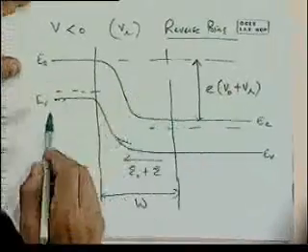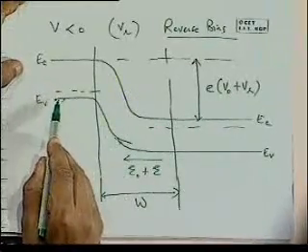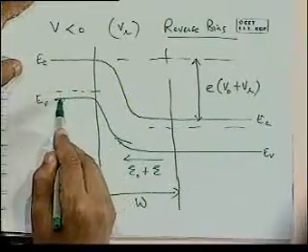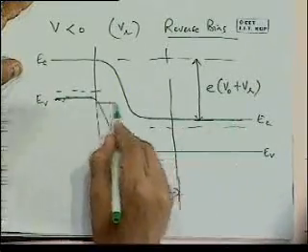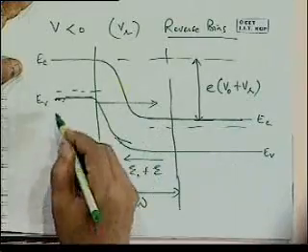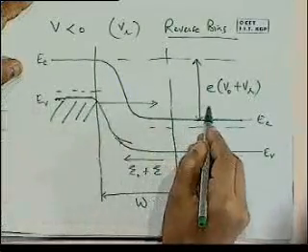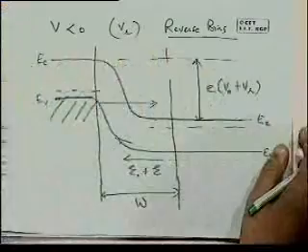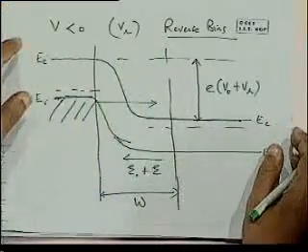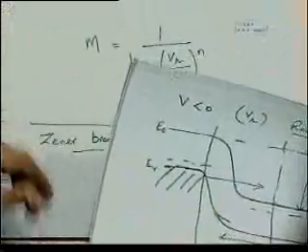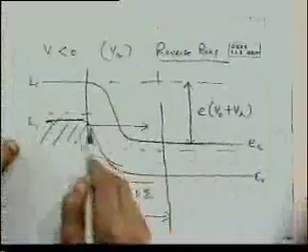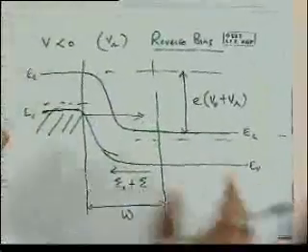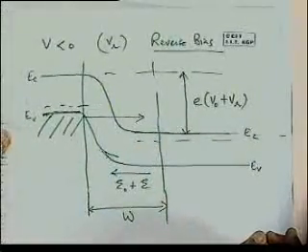What that means is that if we achieve a reverse bias voltage where the valence band here is higher than the conduction band here, we will get tunneling through here, because this side is full of electrons, these are relatively empty, and the depletion layer width is small. So tunneling current is there, which is more than the other current that we have in the regular reverse direction, and that can lead to Zener breakdown, additional current flowing because of tunneling in heavily doped diodes.